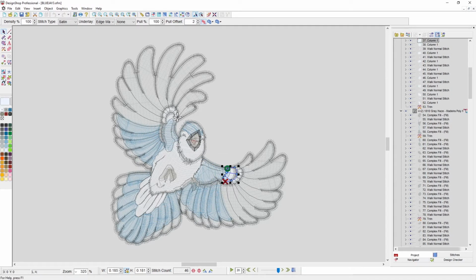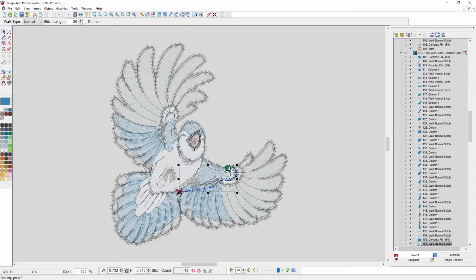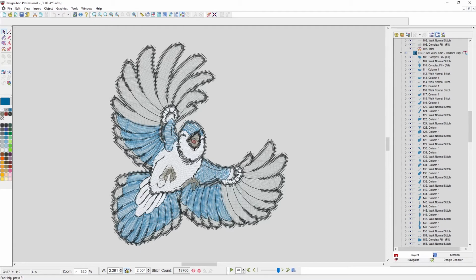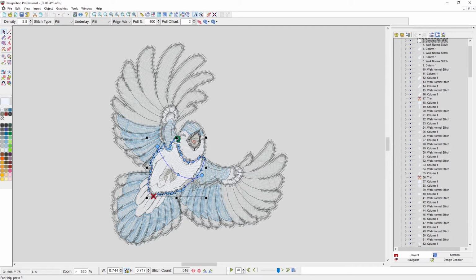And once you reach the bottom, you can't go any farther. Then you can come back up through the layers the same way with next element. So this is select previous element and select next element. That will deal very much with where you clicked. If I click somewhere where there's a lot, you'll get more overlapping pieces, and you can drill down through those. If you select where there's very little underneath of it, no matter how many times I click, there's nothing underneath of it to get to.